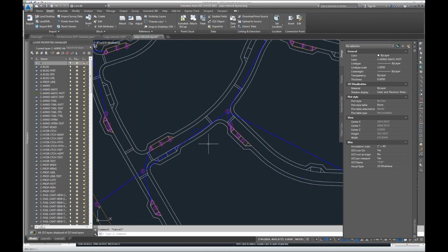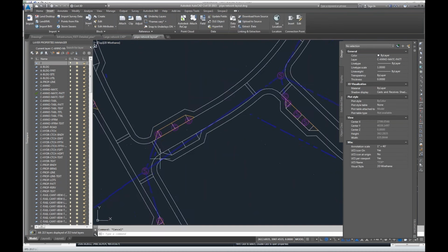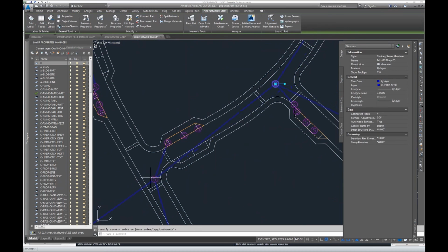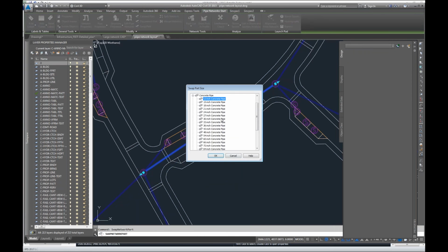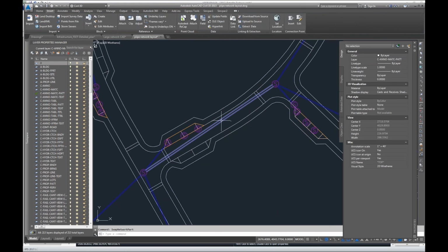The biggest thing I'd see in this model is, well, maybe I didn't lay out the pipe network with as much thought as I should have. Here is a pipe that runs through the sidewalk. Maybe I'll move these manholes more to the edge of the street, for an inlet in line with the road, and so on and so forth. By default, I also start this model with 12-inch pipes. I can upsize those in our software automatically, but maybe there's a specific item where I want to swap the part, as it's called in Civil 3D. So I'll swap this pipe size. Great, so I've made adjustments.